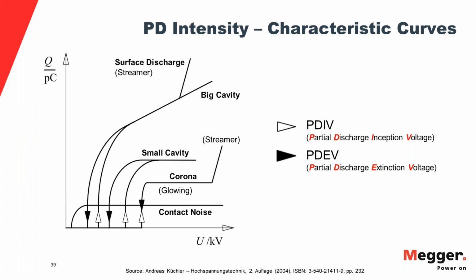So it's less, and it can be 10% less up to 30% less. Those are the extreme numbers that you see. So rule of thumb, you can say 80% of IV typically, with exceptions. It's just an idea. It's not exact. So the partial discharge is ignited, and it goes out at 80% of that.